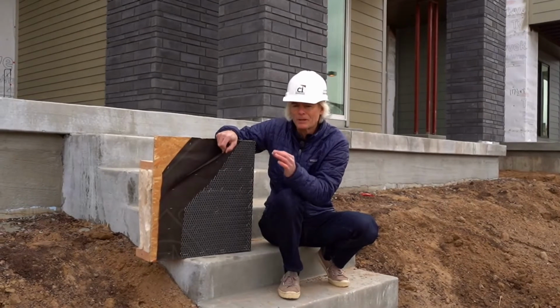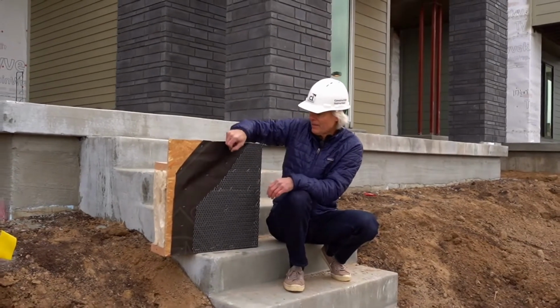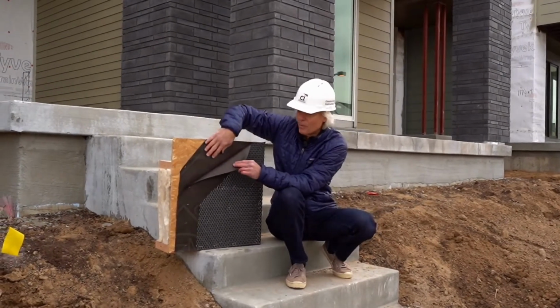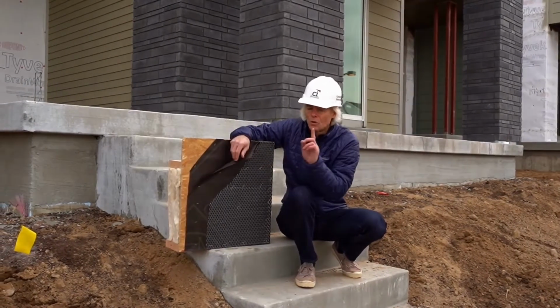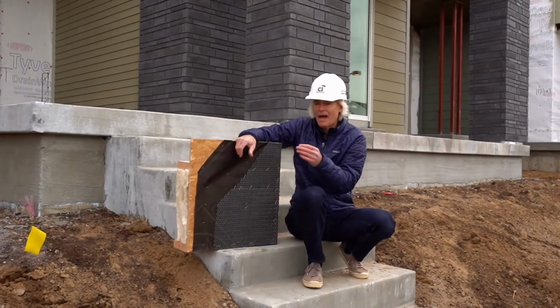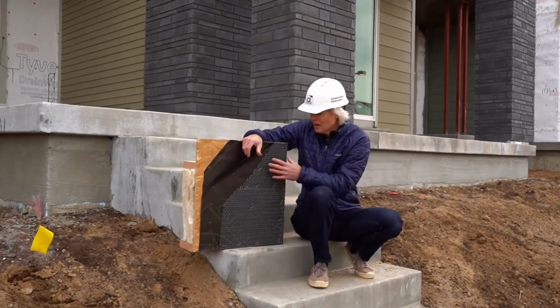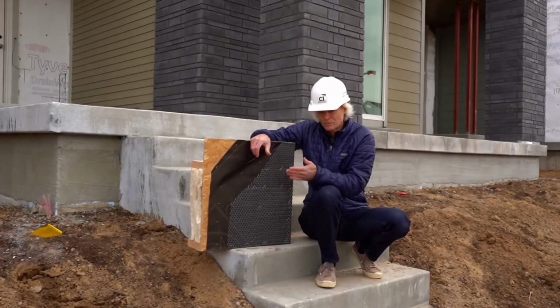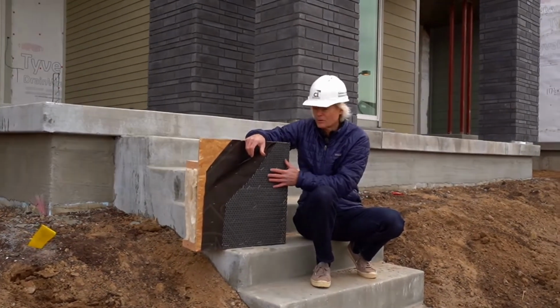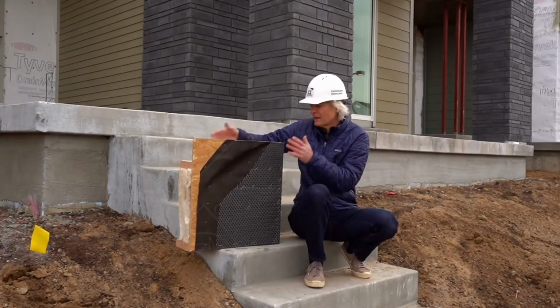Almost by building code you'll see this almost everywhere. This is my weather barrier layer here, and typically connected to different flashing materials, we hope. So we see expanded metal lath, and then we go to a scratch coat, then maybe direct applied stone, or if it goes from scratch coat to brown coat to color coat for stucco, and that's a typical thing.